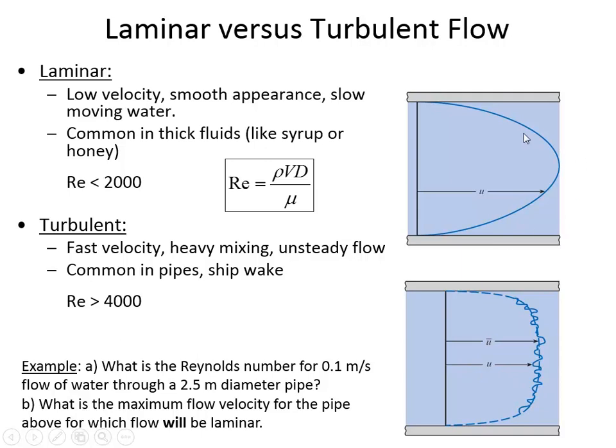What would happen if the pipe itself had rifling? Would that increase this flow rate or decrease it? I think it would probably induce more turbulence, because what you'd be doing is causing the water to rotate as it flows, and so that would probably add resistance to the flow. The best conduits for flow, meaning you get the most flow, are those that are very, very smooth. And so any interruption to that, even if it's a regular pattern like rifling, would just induce more turbulence.